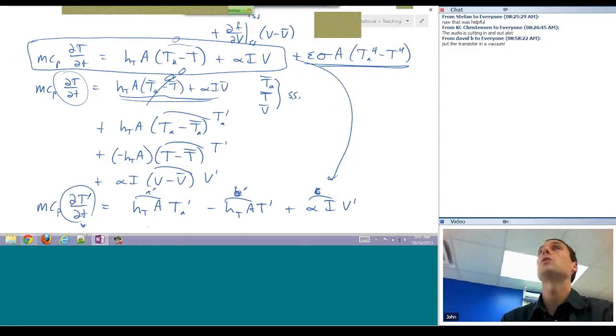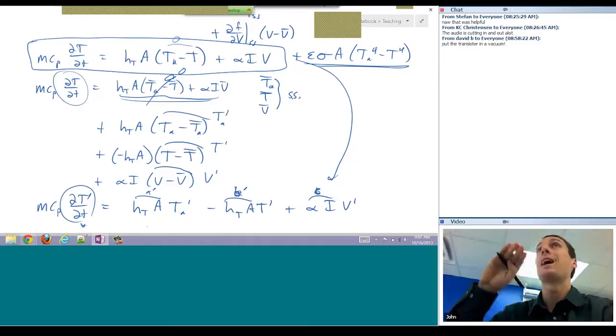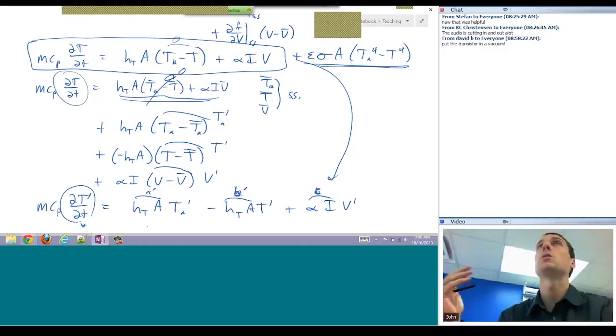What you'd see is more heat transfer as the temperature grows versus decrease. So you'd see that your linear predictive model predicted a higher temperature than was actually the case at higher temperatures, because you don't have that radiative heat transfer away from the device.